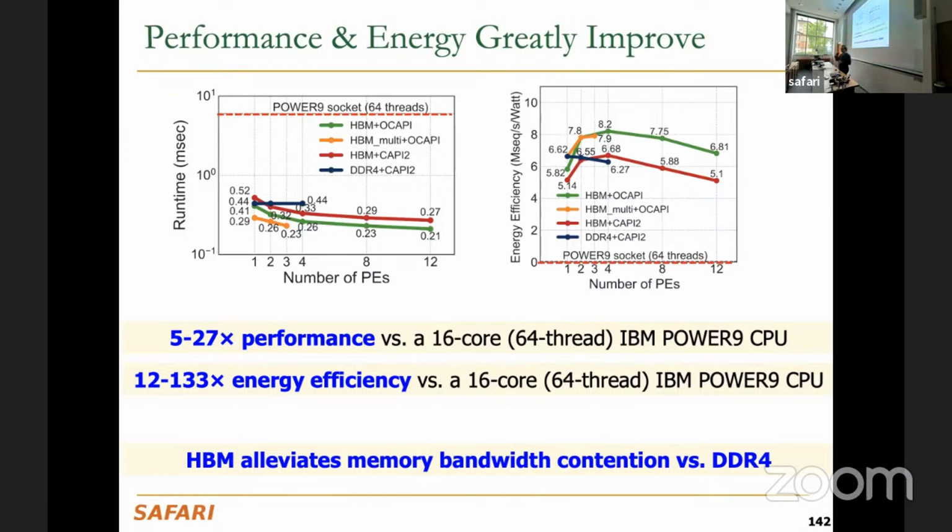So are the modeling and the genome analysis workloads considered, or is it not big enough? So in this particular case, we offloaded specific functions. If you read the work, you will see that it's not the end-to-end everything in the workload. Some of the workload still executes on the CPU side. So it's not perfect. But I think what you're getting at is very fundamental. If you have small memory, you will need to think about the scaling approach to the system, right? So using multiple FPGAs with HBMs, a network of that, is one approach. Very similar to what GPUs are doing today, right? You have GPU, HBM, and then you have a network of GPU plus HBM today.